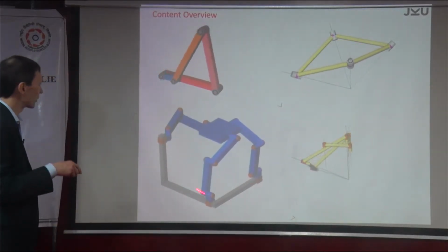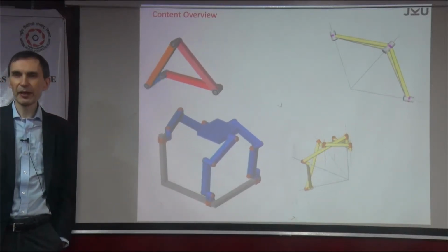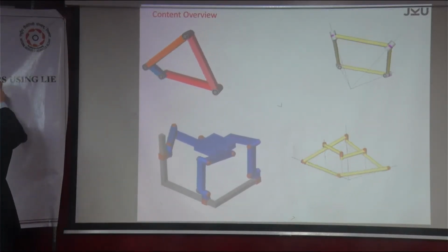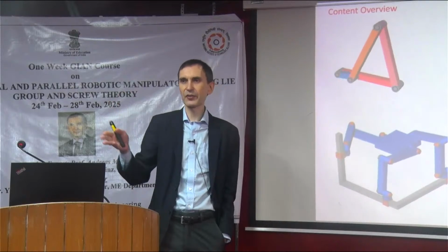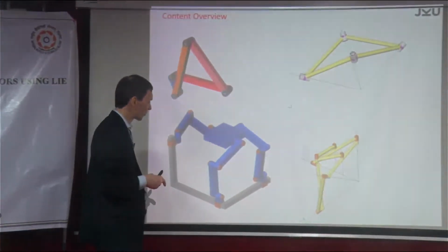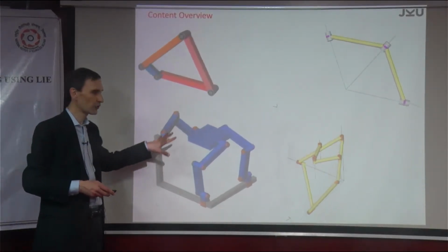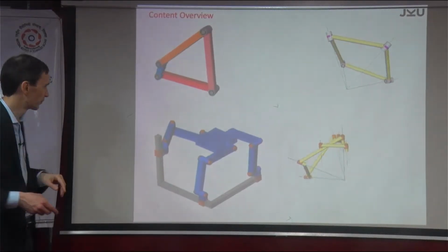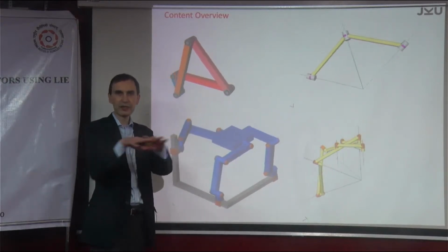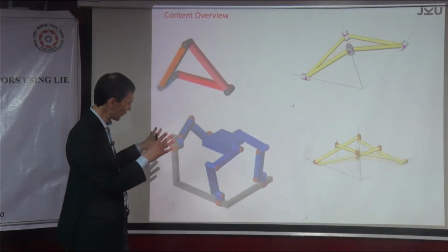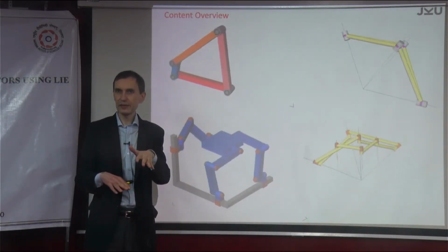This is maybe an example of what we call a robot, and in particular one that is called the parallel kinematic robot. We call this PKM. PKM always stands for parallel kinematic machine or mechanism, and PKM is just shorter to say. So what's particular about this one? Essentially, this is the psi mechanism that goes back to different authors at the same time, by the way. And you can say this is the platform. There is a platform that is to be positioned, right? And if you analyze it, you will see the platform can only translate in space. It cannot rotate. That's important.